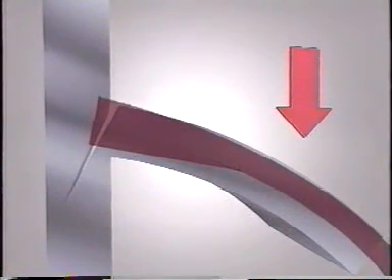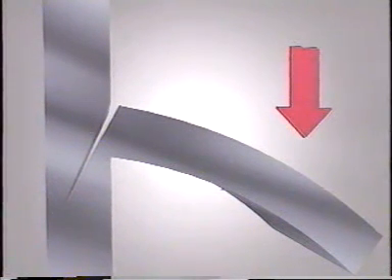Because of the shear stress component characteristic of cantilever loading, the direction of the maximum tensile stress makes a small angle with the axis of the beam. Consequently, a fatigue crack will usually propagate into that portion of the beam within the fixed mounting.